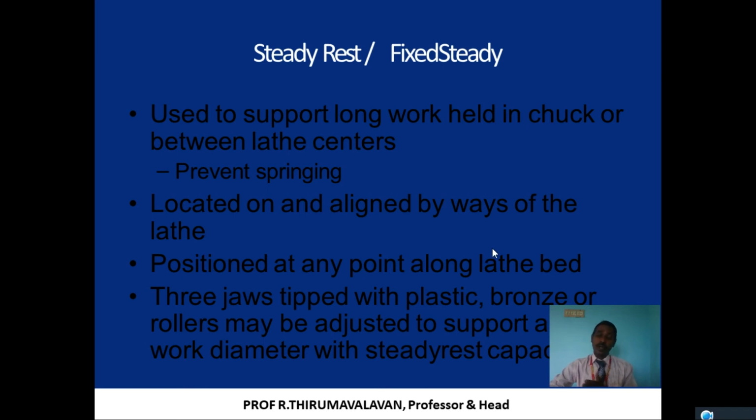The rest follows along with the workpiece. It is fixed near the tool, side by side. When the tool applies force, the workpiece tries to bend. That can be avoided by giving an opposite reaction. On the opposite side there is a support, and that comes through the follower rest.